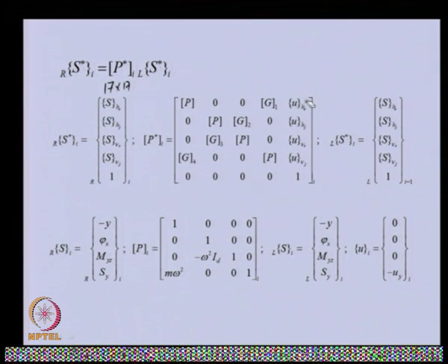So, here also we have the unbalance component in the horizontal direction, real part, imaginary part, and vertical direction, real part and imaginary part. But the gyroscopic couple terms are coming in these G matrices G1, G2, G3, G4.